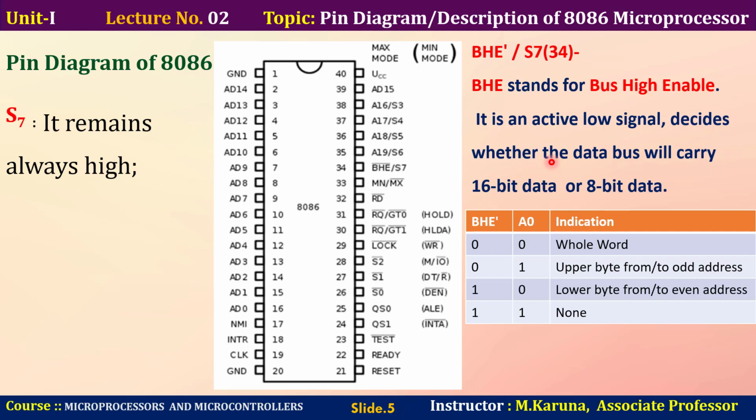So whenever interrupt occurs through this pin, processor immediately stops its execution and jumps to the particular requested interrupt or jumps to the IO device based on the interrupt request. Okay, so that is about non-maskable interrupt and interrupt request. Both are active high signals.